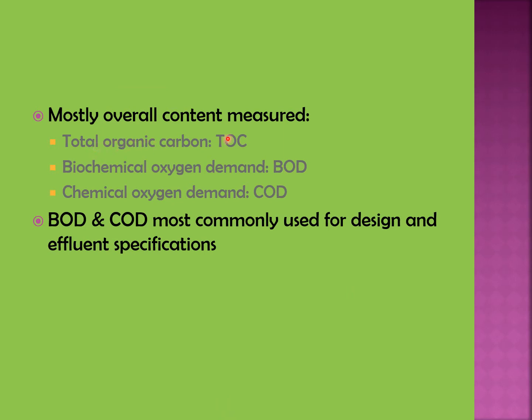Overall organic content is measured as total organic carbon, TOC, biochemical oxygen demand, BOD, and chemical oxygen demand, COD. Among them, BOD and COD are most commonly used for design and effluent specifications. In this lecture, we will give priority to BOD and COD.